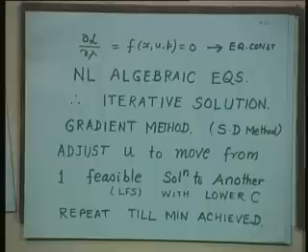These all three are non-linear algebraic equations. Luckily there is no time involved here like stability, no differential equations. But again an iterative solution is required because they are non-linear, highly non-linear. Since it is an optimization, it is no longer a plain load flow, so we need to have an optimization technique. An optimization technique which we use here is the simplest possible, called the gradient method or steepest descent method.